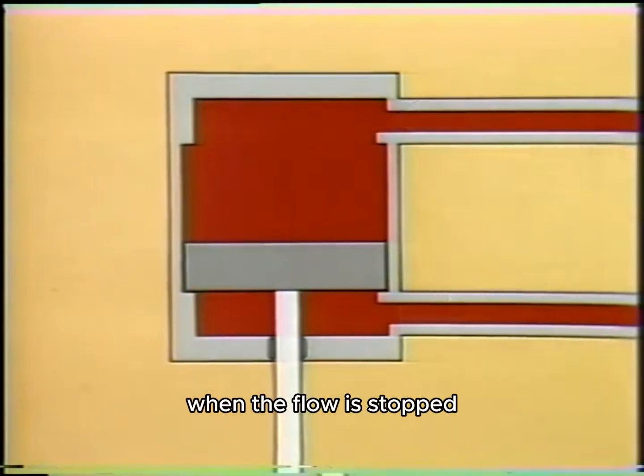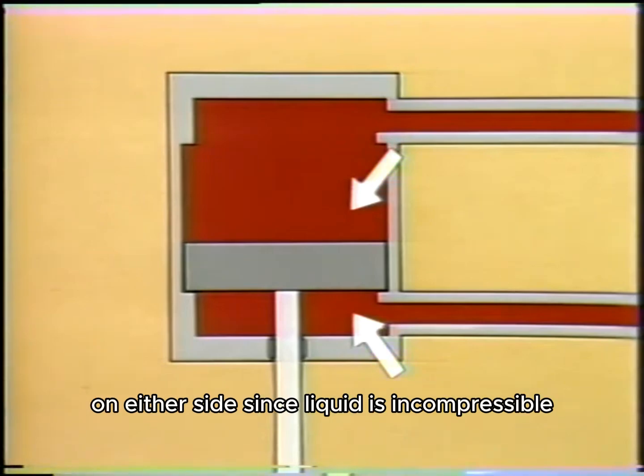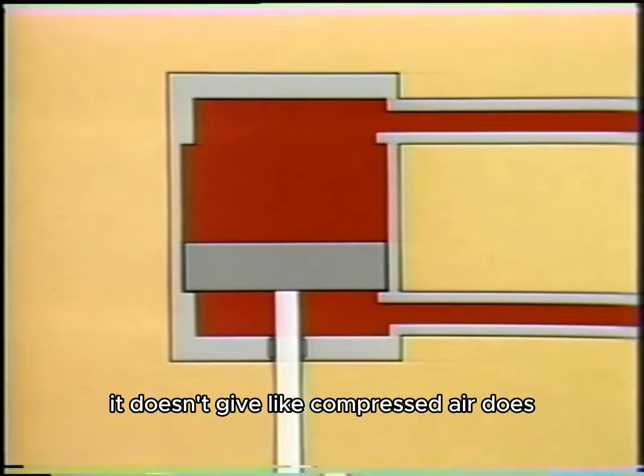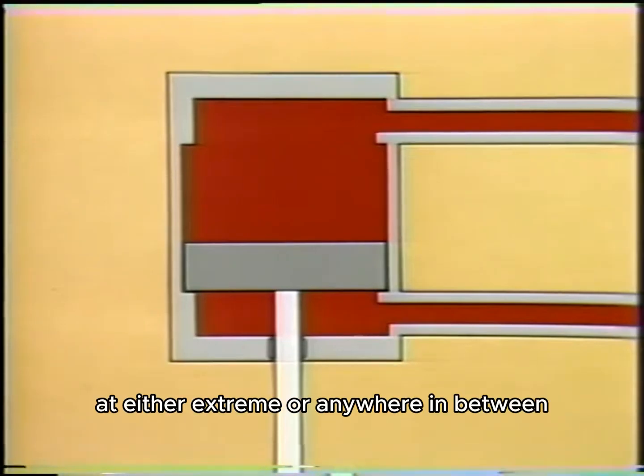When the flow is stopped, the piston is locked in place by the trapped liquid on either side. Since liquid is incompressible, it doesn't give like compressed air does. Once the actuator is in position, at either extreme or anywhere in between, that's where it's going to stay.